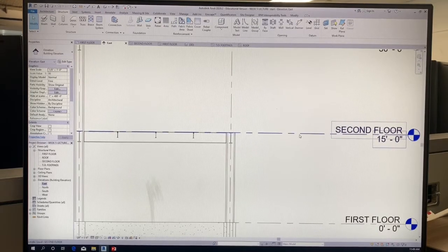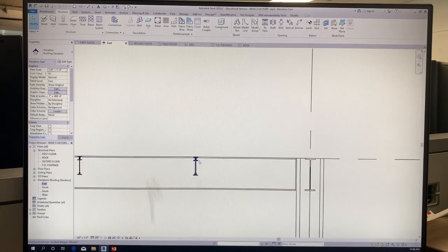All right, so if I put a floor slab on the second floor, it's going to intersect these beams and this joist. So what I have to do now is drop these beams down. How far down? The thickness of my floor slab. For this exercise, as well as yours, we're going to use the 3-inch lightweight concrete on 2-inch metal deck floor slab. So that's going to be a total thickness of 5 inches. So we got to drop all our beams down by 5 inches.